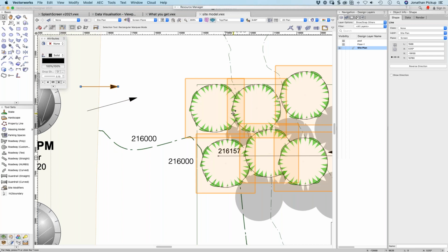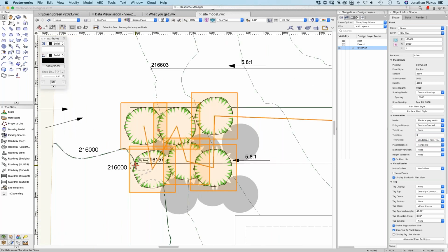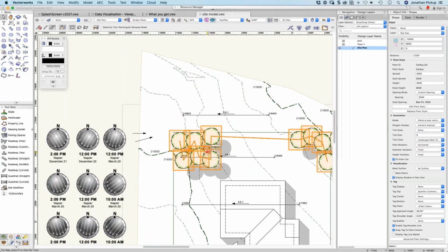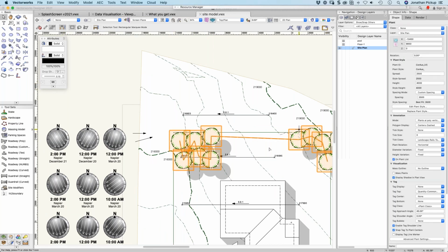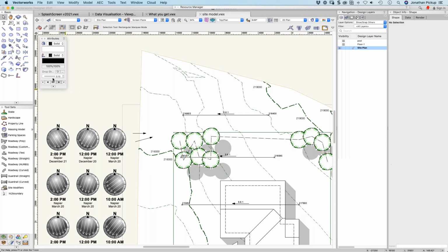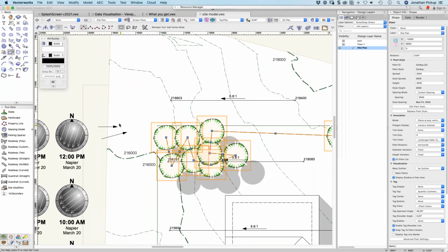Now let's turn on polygon display, centers dashed. Now sometimes when you do this, Jane, you end up with arrowheads on everything. Yes, very annoying. Go back to here, turn that off, and then do it again. Let's edit this. No, I'm not getting arrowheads at the moment, but that's usually the cause of it, that your default has the arrowheads turned on.